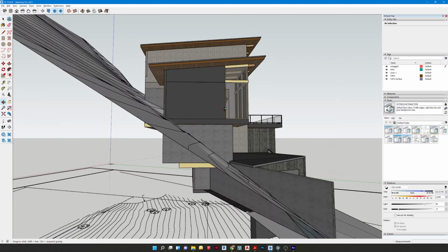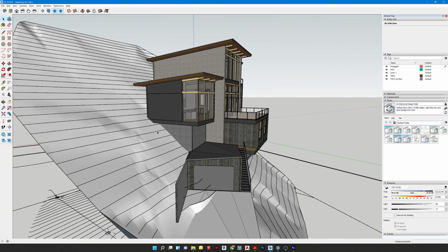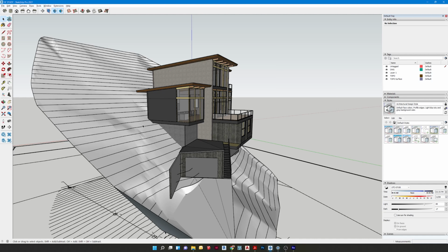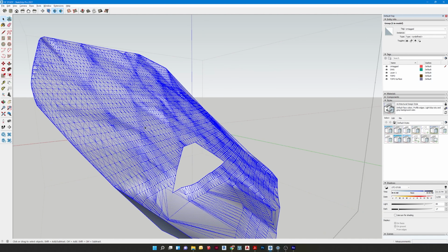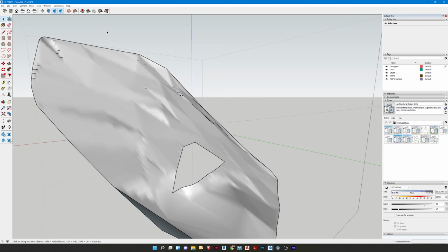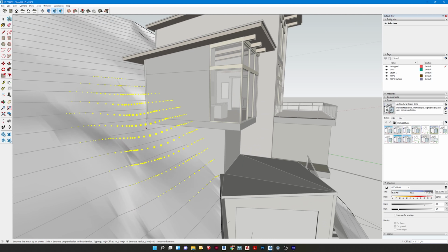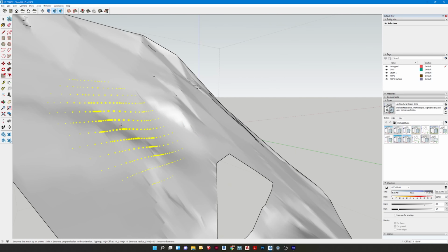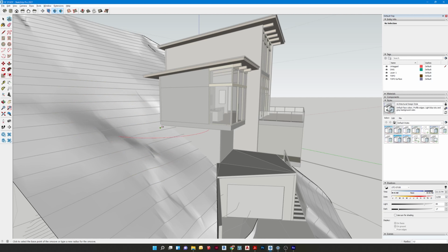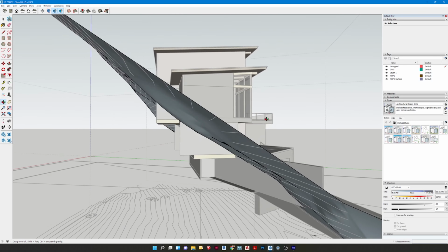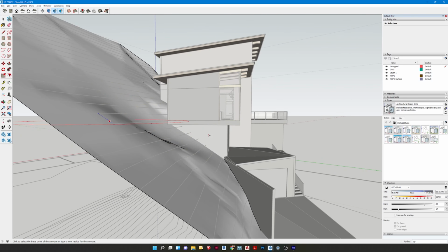And I still have a couple areas. You can see this corner up here, how that's poking through. So I'm going to regrade that slightly by also using the sandbox tools. So we'll click into that, and you don't have to go all the way. So don't click this far, just click in and then select Smooth. And I have my radius, you can see in the bottom right corner, at 15 feet. So that's pretty good for this. And then just select one of these lines and you can drag that down. And usually I select a larger area just so it looks natural, and that's how you regraded that a little bit. And we're clearing that, so maybe I'll come down a little bit more.